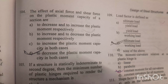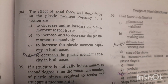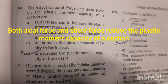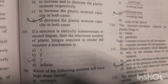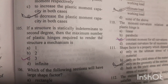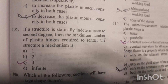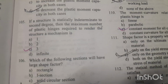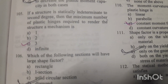Question number 104. The effect of axial force and shear force on the plastic moment capacity of a section are to decrease the plastic moment capacity in both cases. Option D is right answer. Question number 105. If a structure is statically indeterminate to second degree, then the maximum number of plastic hinges required to render the structure a mechanism is degree of static indeterminacy plus 1. 2 plus 1 equal to 3. Option C is right answer.